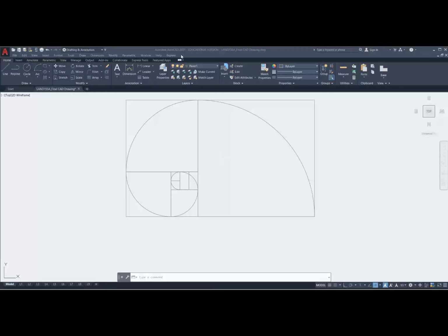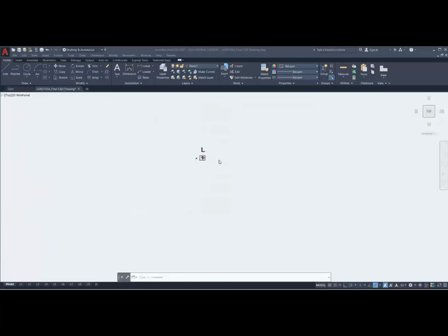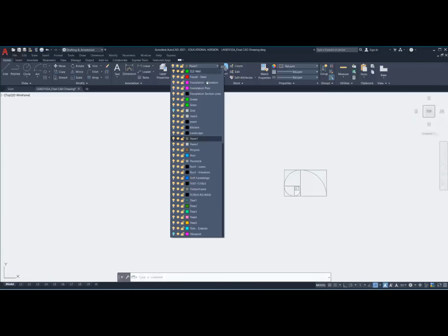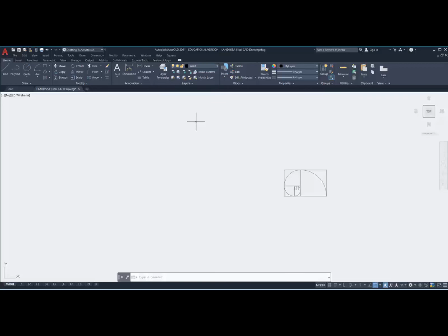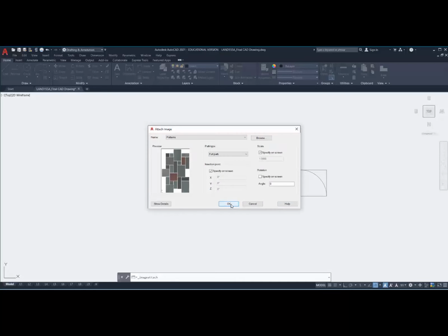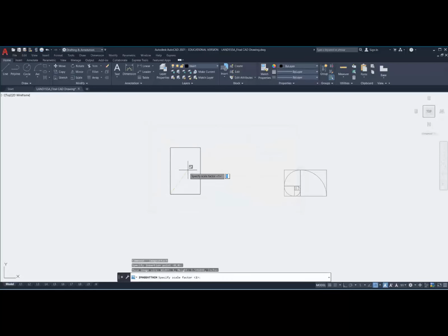I've got this already set up where I've got the layers designed specifically to accept the image. And I have an insert layer and a pavers layer and all these different applications ready to go forward. So this is something that you would pre-do. And then you'd save that graphic image and insert it just like we have before, into our CAD file. So I have the insert layer current. Now this is a raster image, it's a JPEG. So as a raster image, unlike a PDF, it has a slightly different insertion methodology, but only in the selection of the first step. The rest of it is exactly the same, and you can see it here.